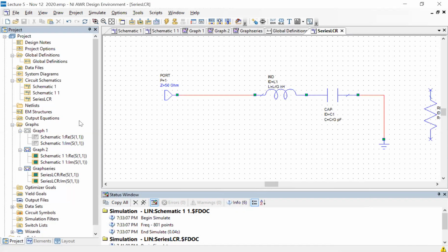In fact, just as you were saying it, I was trying to think about what the answer would be. So it's obvious that it cannot be in series, right? Because if you put something in series, it's going to become part of the resonance circuit and completely modify it. But it is possible to put it in parallel. However, that might also have a much bigger loading effect. There's actually another way of doing this, which might be a lot more practical. It involves a slightly different version of components we have discussed so far. I mean, we have not considered this.